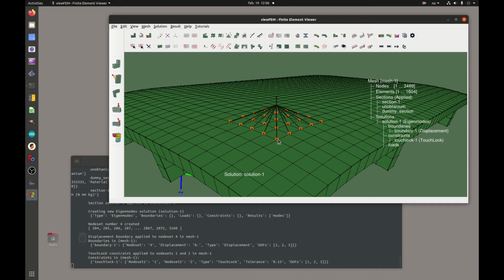In this case, you can set the tolerance too high. So too high in this case would be 1, because there's a distance of 1 between neighboring nodes, and you only want these two nodes to be within the tolerance of each other. Otherwise, the solver will try to create several multipoint constraints on the same node, and that will crash the solver.